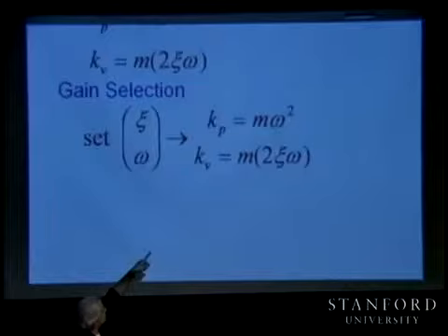In fact, if you're lucky, you can go to 10 hertz. I mean, this would be great. So when we go to 1600, this is really nice. 40 divided by 6. Well, in practice, you start with very low gains, and you start tuning your gains up, and suddenly you're going to hit that noise, start to vibrate, so go down. But we will see some ways of doing this in a more precise way. But again, what you are seeing here is Kp and Kv.